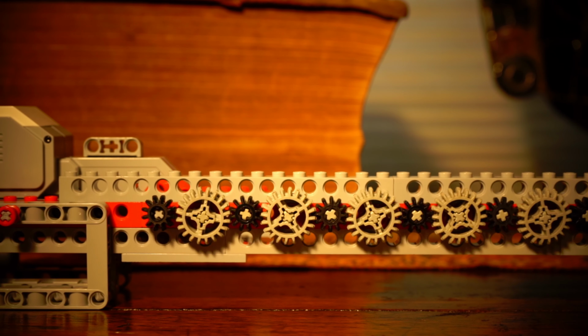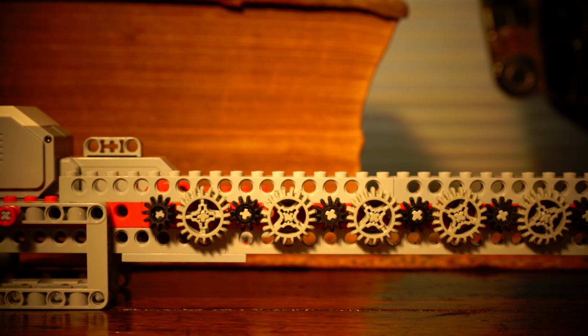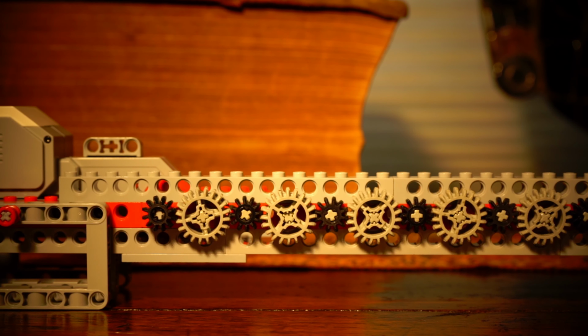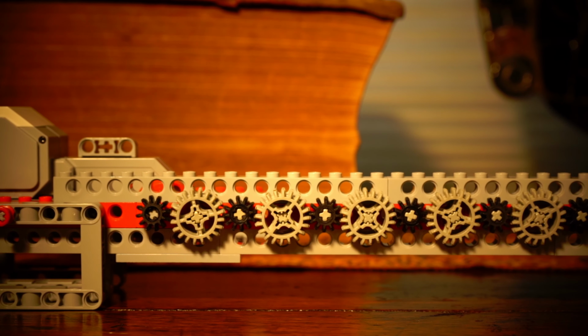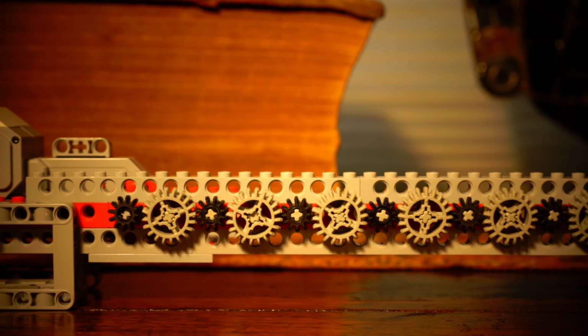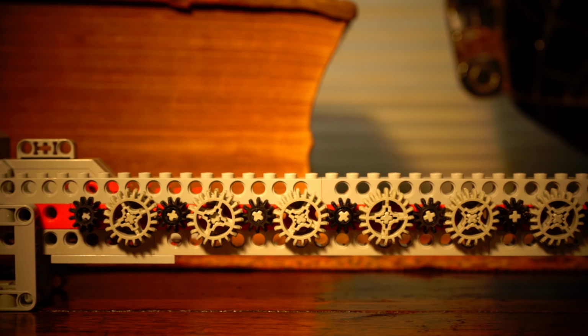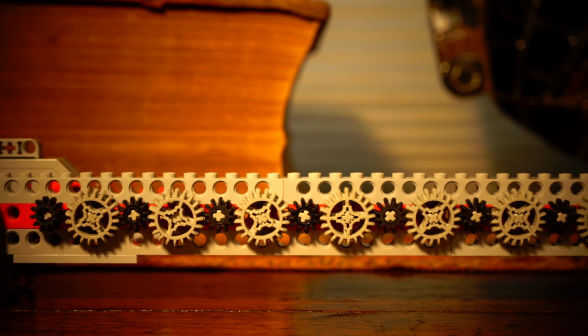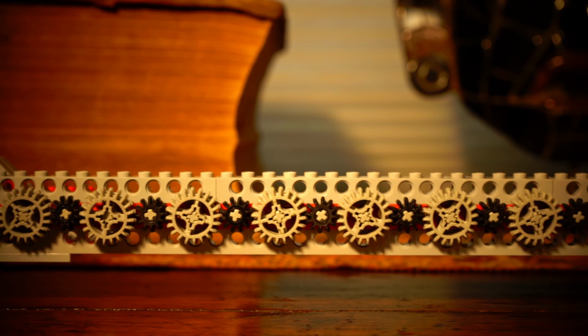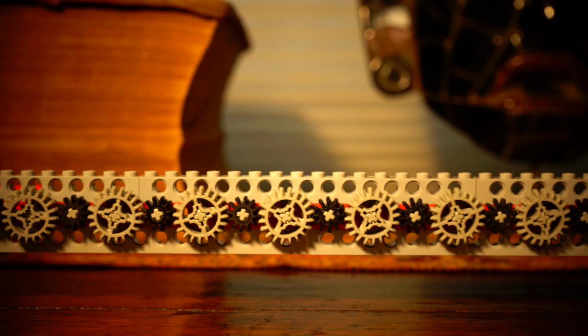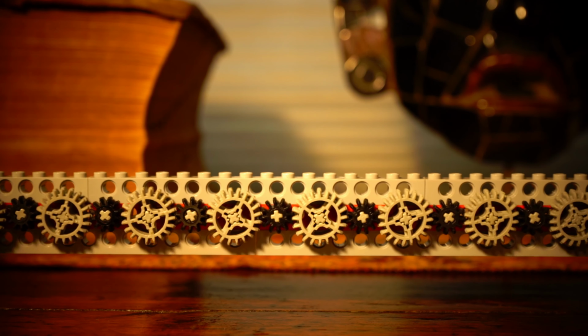No gear train, whether simple or compound, is ever 100% efficient, so some torque and power will always be lost. But where gears mesh well, in which the gap or overlap between two gears is minimized, gear train efficiency will be maximized. For this reason, goodness of fit between gears should always be evaluated, and can be calculated for all gears in a simple gear train. Only simple gears are discussed in the remainder of this video.